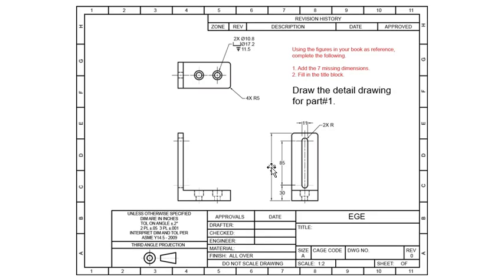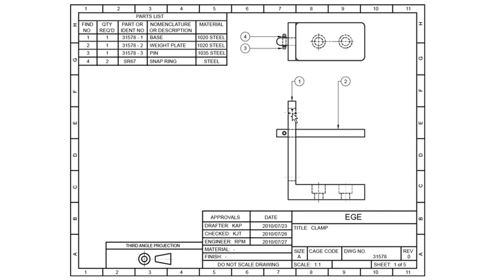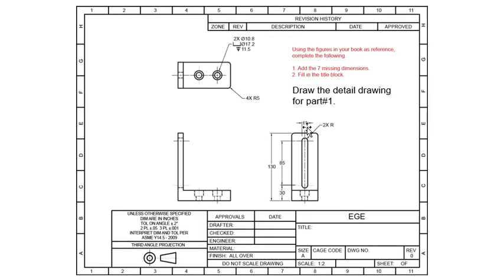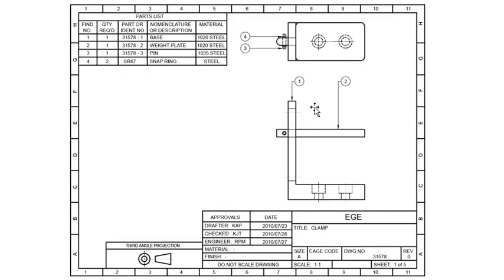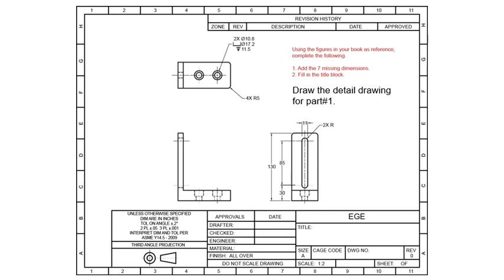Alright, then we're going to draw the first part. So the very first part is this one. So when you go there, balloon, this one. So we're going to draw that one in 1, 2, 3 views. So here we put the necessary information of that. Since we're doing the part, we would draw the detailed drawing. This is just assembly, so you don't need the details. Here, detailed drawings for the first part.